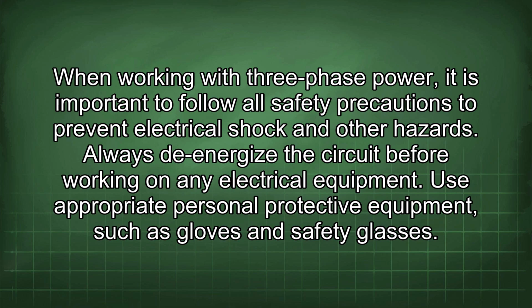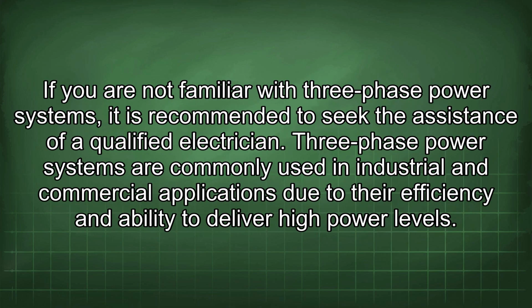When working with three-phase power, it is important to follow all safety precautions to prevent electrical shock and other hazards. Always de-energize the circuit before working on any electrical equipment. Use appropriate personal protective equipment, such as gloves and safety glasses. If you are not familiar with three-phase power systems, it is recommended to seek the assistance of a qualified electrician.